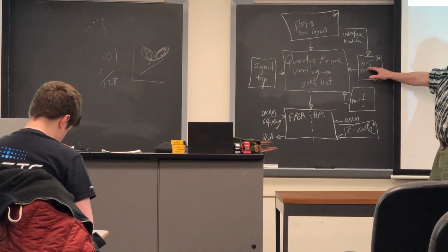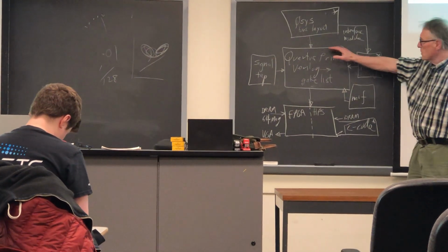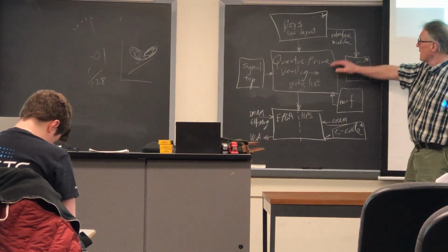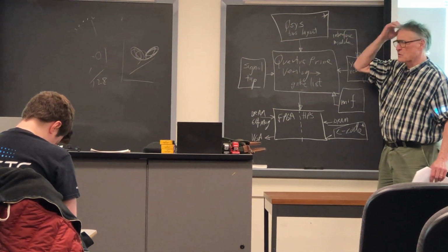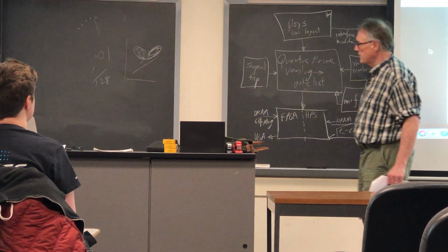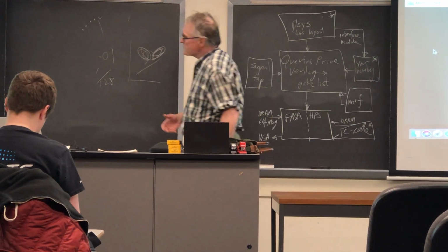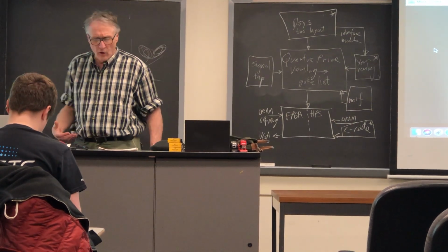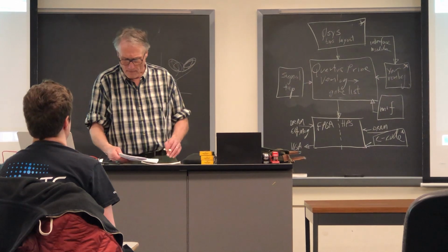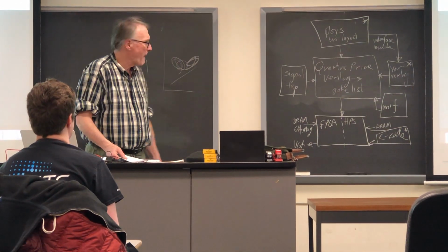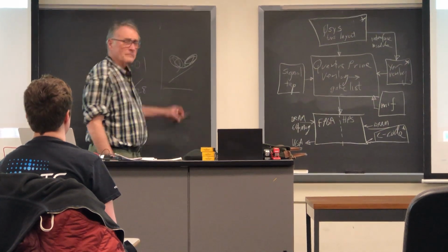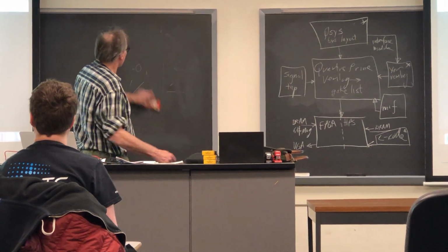There's going to be Verilog source, which glues together all of the hardware on the FPGA. And there's going to be a Qsys source, which is really a graphic layout, that tells Verilog how to hook all these pieces together. Any questions?